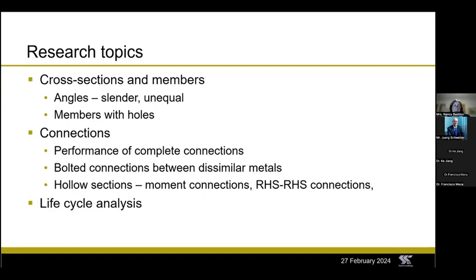Stainless steel, you may remember, has a very low thermal conductivity, and so it's appropriate for some applications in energy efficient structures. And for these, you sometimes have long slotted holes. So that's another area where research is needed. Of course, connections, there are quite a lot of possible research topics still needing work. Complete connection performance, connections between carbon steel, often stainless steel is bolted or welded back to carbon steel. And hollow sections, the guidance in AISC 370 on hollow sections is somewhat limited. There are certain topics such as moment connections, plate to hollow sections, and rectangular hollow section connections, which is missing. And these are all the types of connections where it's governed by deformation rather than strength.